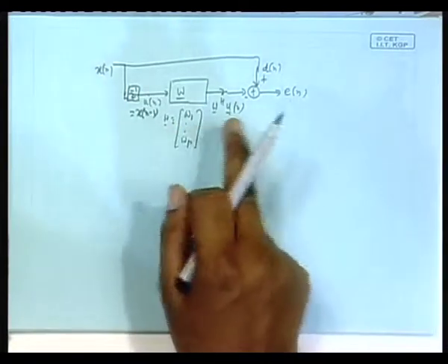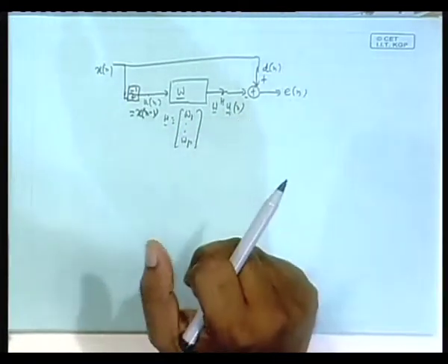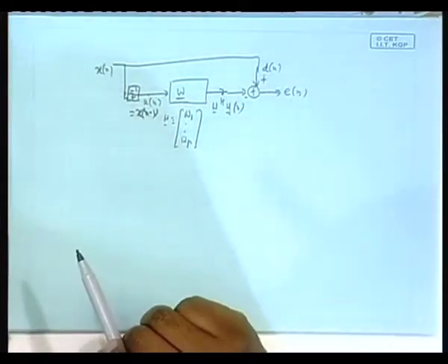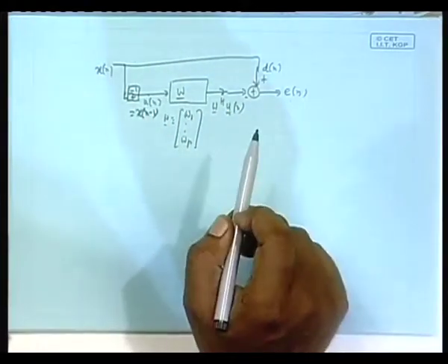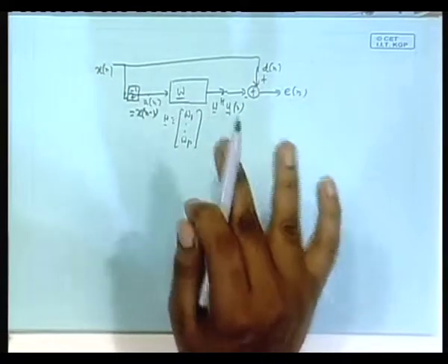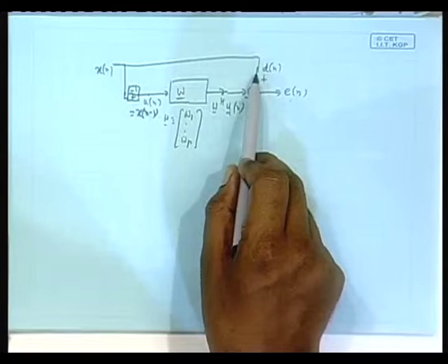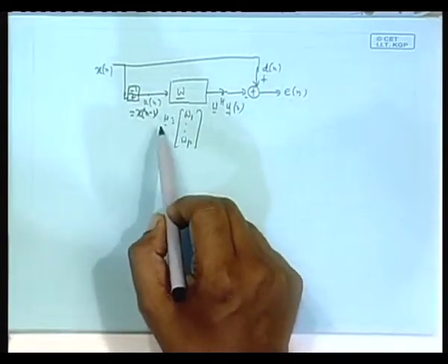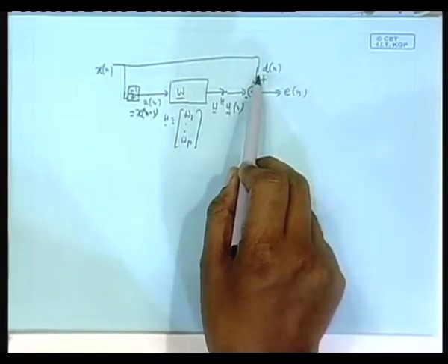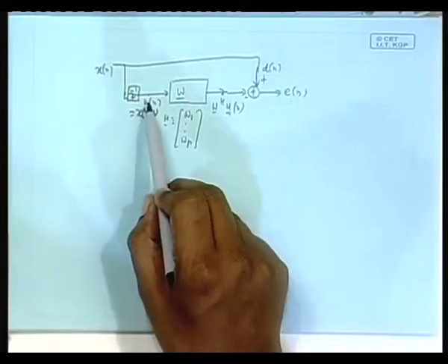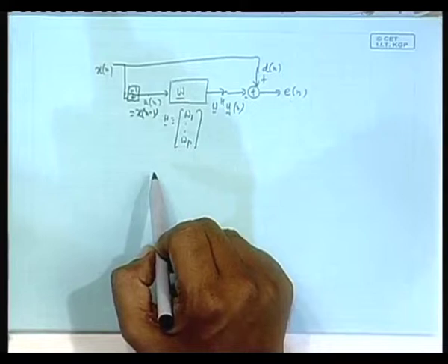So, this is a special case of the general optimal filtering problem, where Dn and the input are generated from some xn. This is our linear prediction problem, because what you are doing is trying to estimate xn as a combination of the past samples, or rather you are projecting xn on the space spanned by xn minus 1, xn minus 2, dot dot dot, xn minus p.